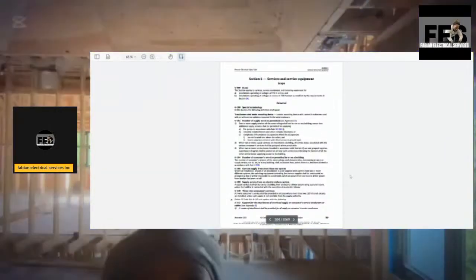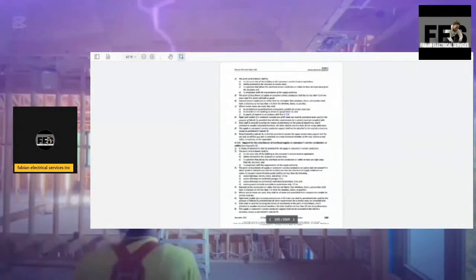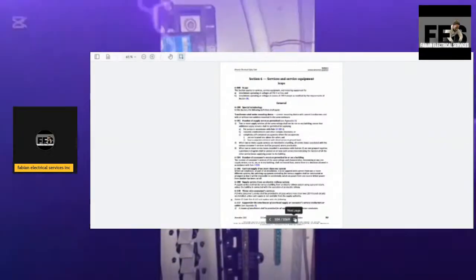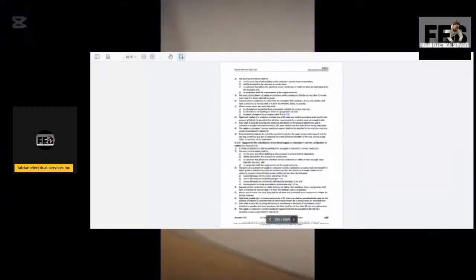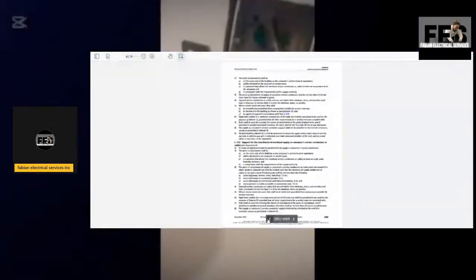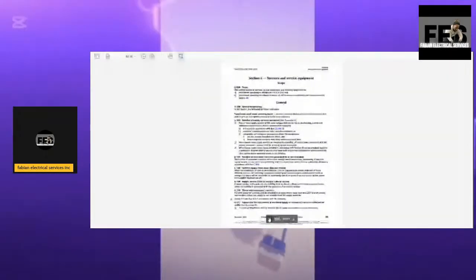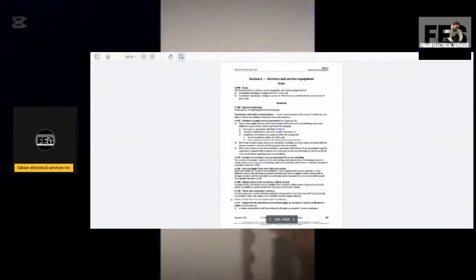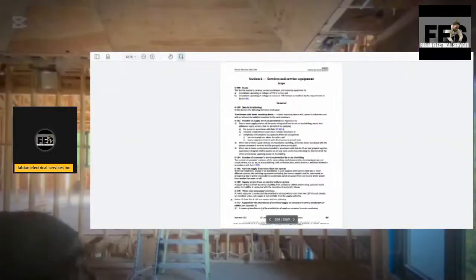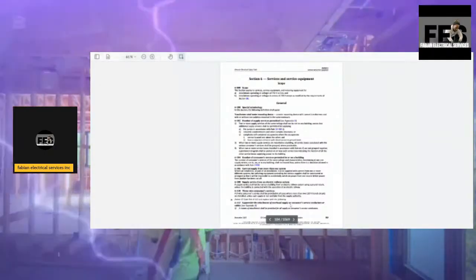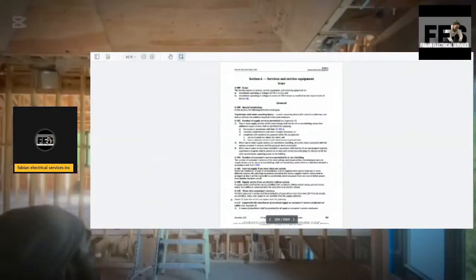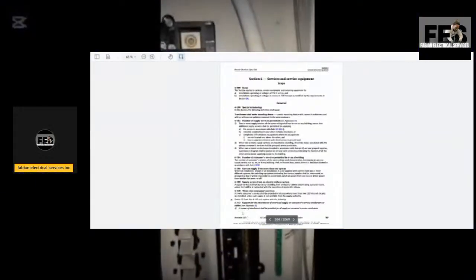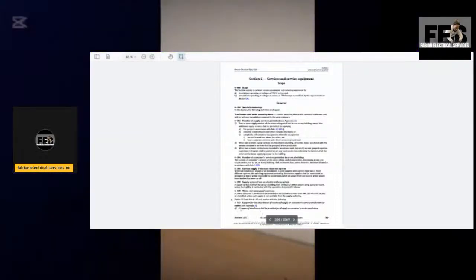So that's not the rule that I want to see. So I'm going to shift that over here. Okay, so at the bottom here, 6-112, that's the rule: support for the attachment of overhead supply or consumer service conductors or cables, and that's going to send you to Appendix B. You simply head over there and look for the information that is being given.